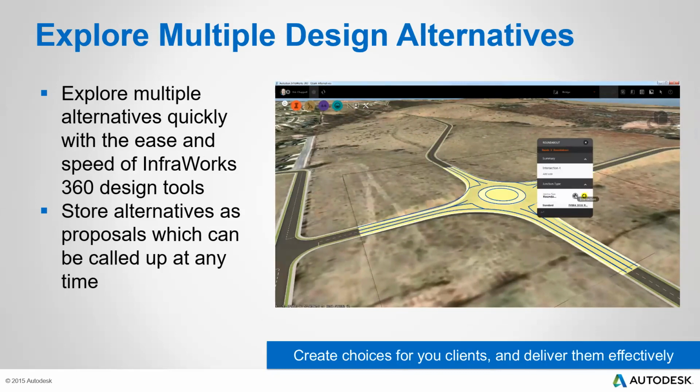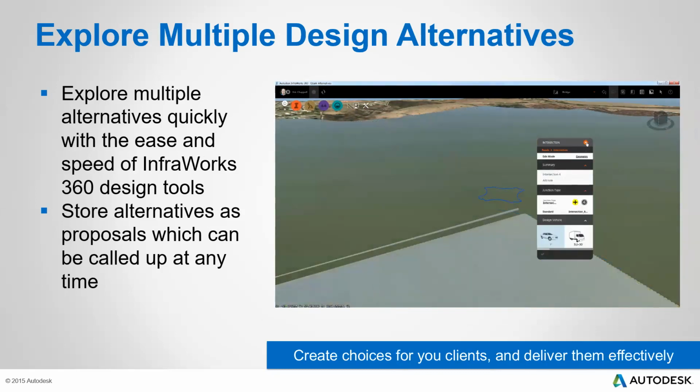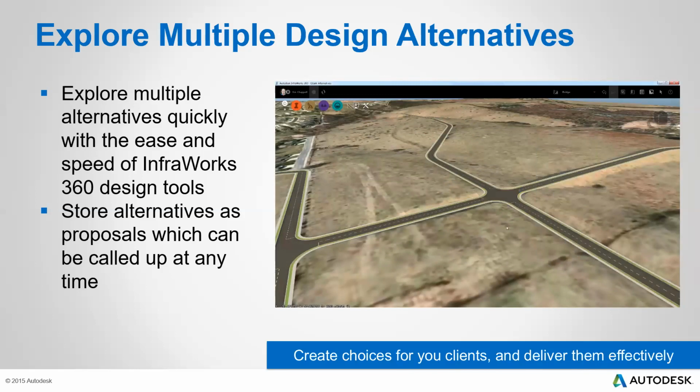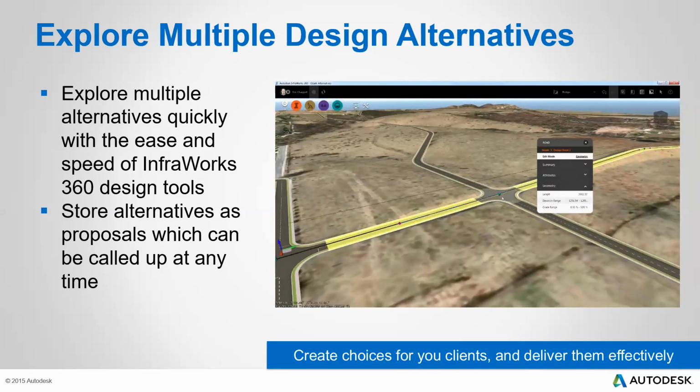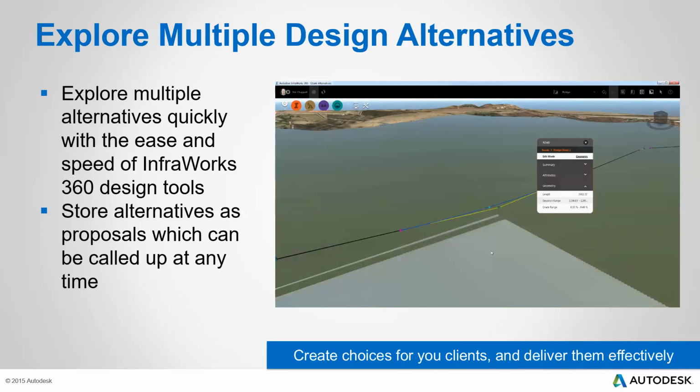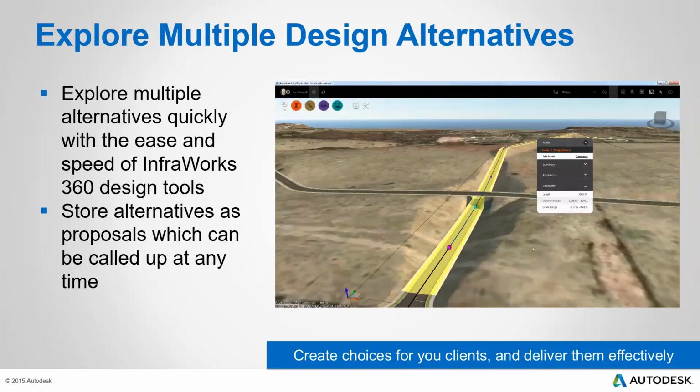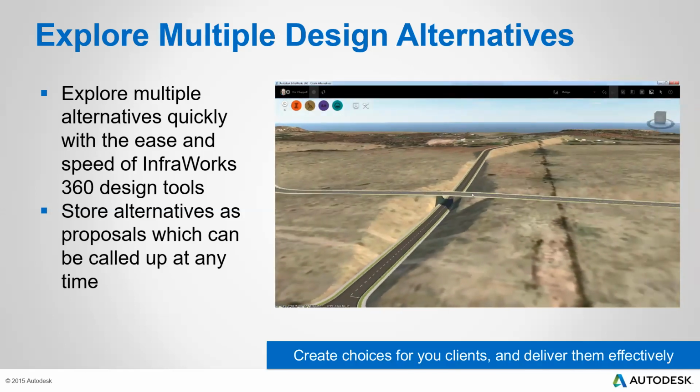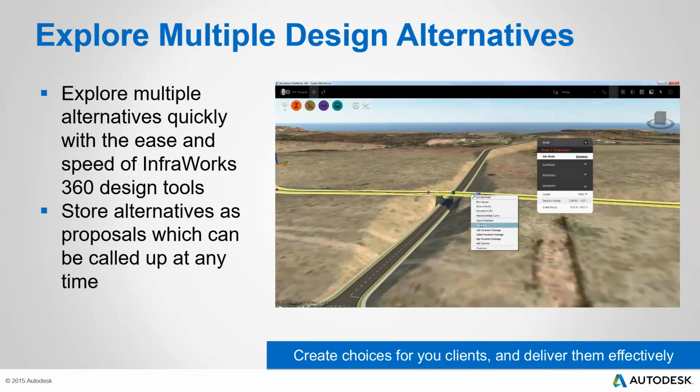And Infraworks itself has preloaded design vehicles that you can use to perform the analysis on that particular intersection and see even the minimum vehicle and maximum vehicle sizes, which can easily maneuver on that particular intersection without running on the road curbs. And you can even tell is it possible for you to apply an overpass or a bridge on that road to avoid the interference of the traffic on those different roads.